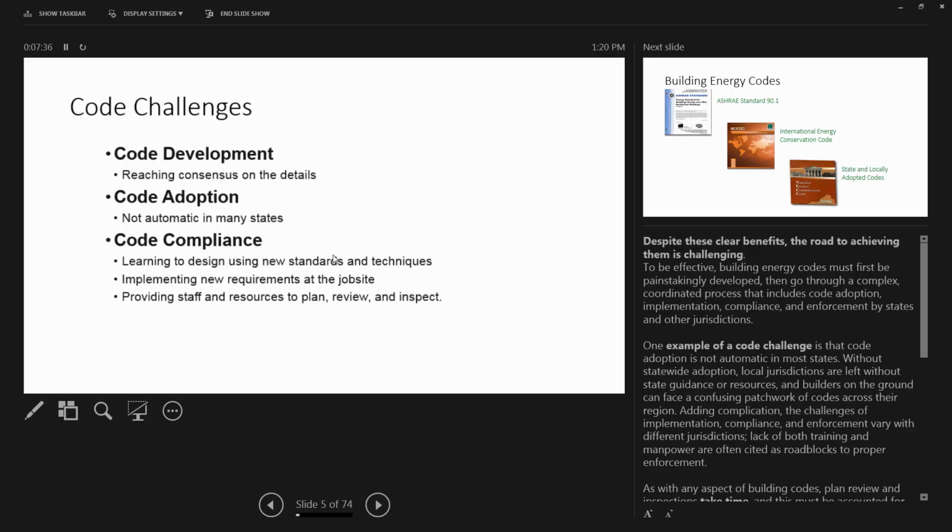The way that they address a lot of the building codes is that the ICC creates the code, the ICC administers the code, they do updates to these codes every 3 years. So as soon as a code gets completed, they almost immediately start taking comment on the things in the code that they'd like to have updated, changed. They have a public comment period of about 18 months. It takes a long time to get them done. Once the ICC finishes the codes, they get approved, but they're not necessarily adopted, and I'll talk a little bit more about that. It varies from state to state.